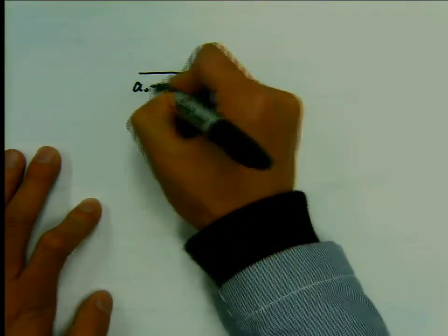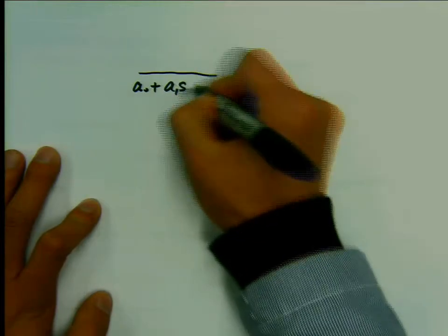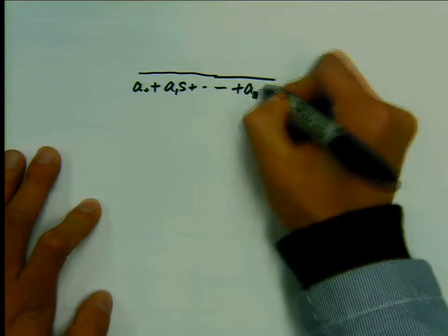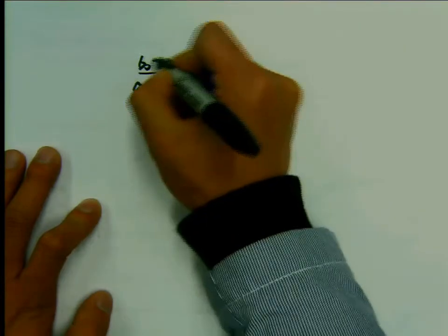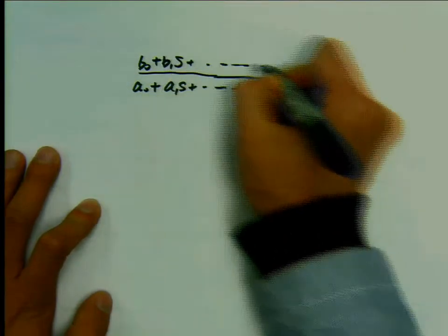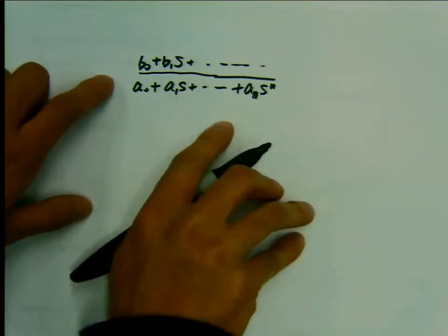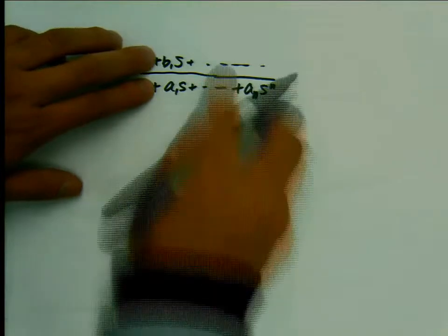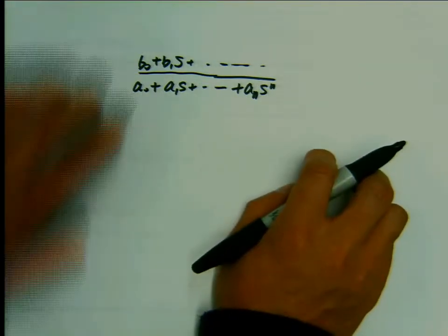Following what you said, if in the transfer function it is in the continuous time case, it's inconvenient to write it this way. This is not convenient because it's possible both of them are zeros, and you get these confusions of orders.